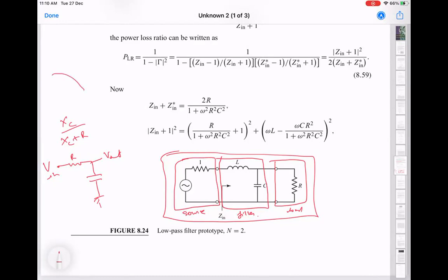Now, this of course uses a resistor here, which we don't want because we don't want the filter necessarily to absorb power as well. But the same function can be obtained if you put an inductor here as well. In fact, that sort of doubles the effect, because now the capacitor going to 0 impedance is also there, but the inductance is also increasing in impedance, right, as we go to higher and higher frequencies. So this ratio, which is going to be now XC over XC plus XL, this will again go to 0, in fact, slightly faster.